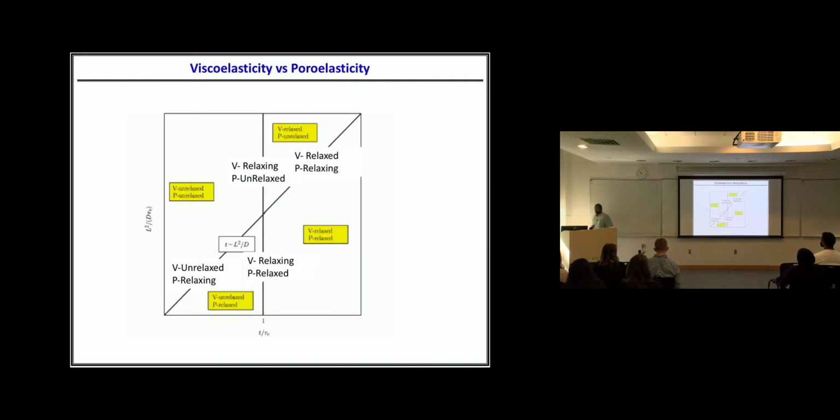Just very quickly, without looking at the board, what's the time scale of poroelastic relaxation? Look at me, not at the board. Abby. Very good. And the time scale of viscoelasticity is an intrinsic time scale. We don't know what it is. It's a competition between these two. So if I test bigger samples, will I be looking at poroelasticity or viscoelasticity? Poro, because the bigger the size, the more time it takes for the fluid to flow. So you will be looking at poroelasticity.